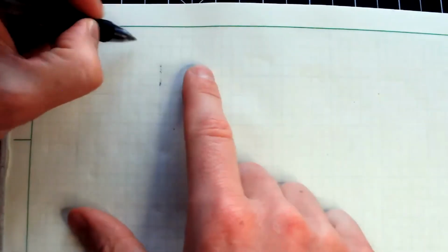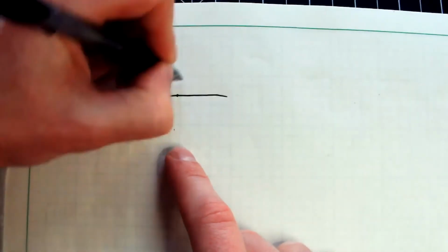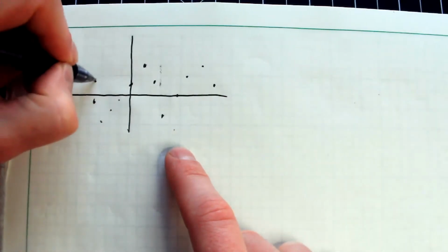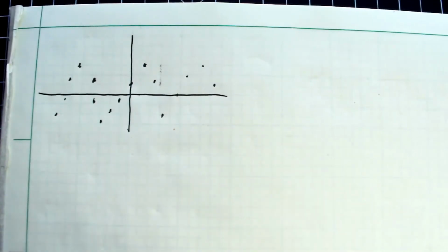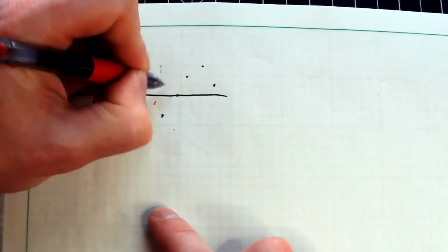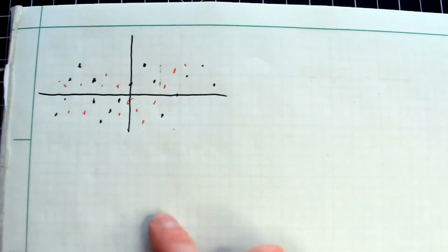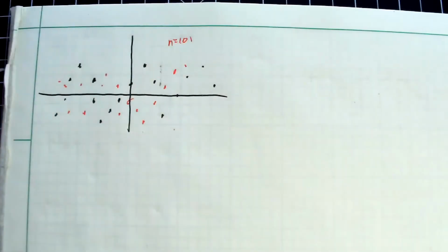So this is all in the lab, but I wanted to walk through this just to emphasize why this little method works. So what you'll have are a bunch of samples, and I'm just gonna invent a bunch of samples like this. Assume this is your reflection coefficient as measured by the nano VNA, and just bear with me and pretend that there's 101 of these samples here. So you have a bunch of samples in this array, and there's n equals 101 of them.